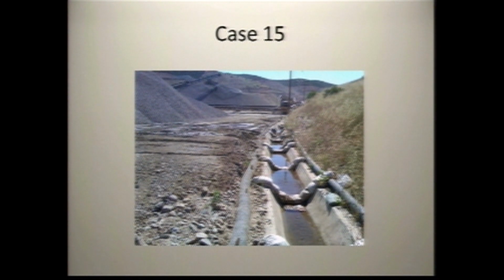What would be the big red flag here that should be catching your attention? Note that it's a nice sunny day. There's water in that ditch, yeah. We just spent a lot of time talking about non-stormwater discharge. This was just continuously running into the storm drain system.